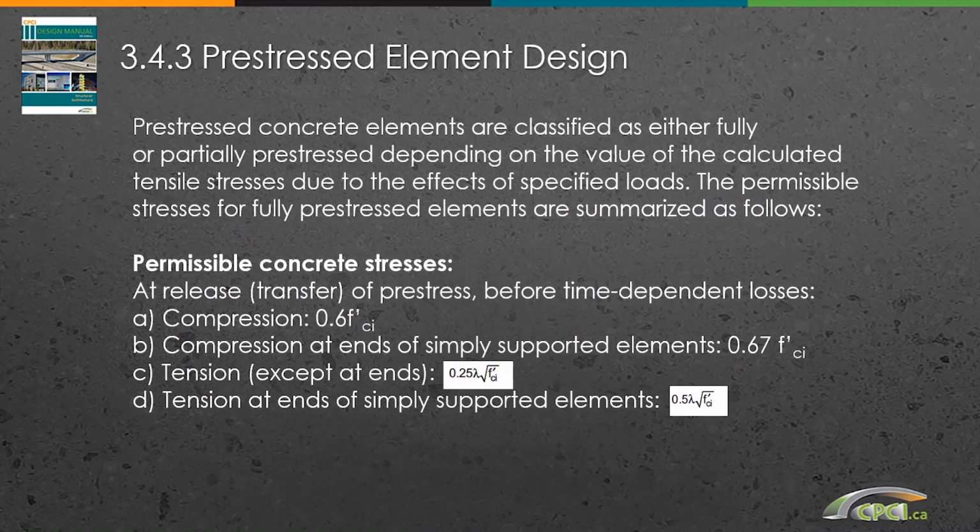For pre-stressed element design, obviously, one thing that we always check are the stresses of the concrete's top and bottom fibers at release, at erection, and also under full loads. And the codes spell out exactly what kind of stresses we cannot exceed in each and every case. And these are the values that need to be followed and obeyed all the time.